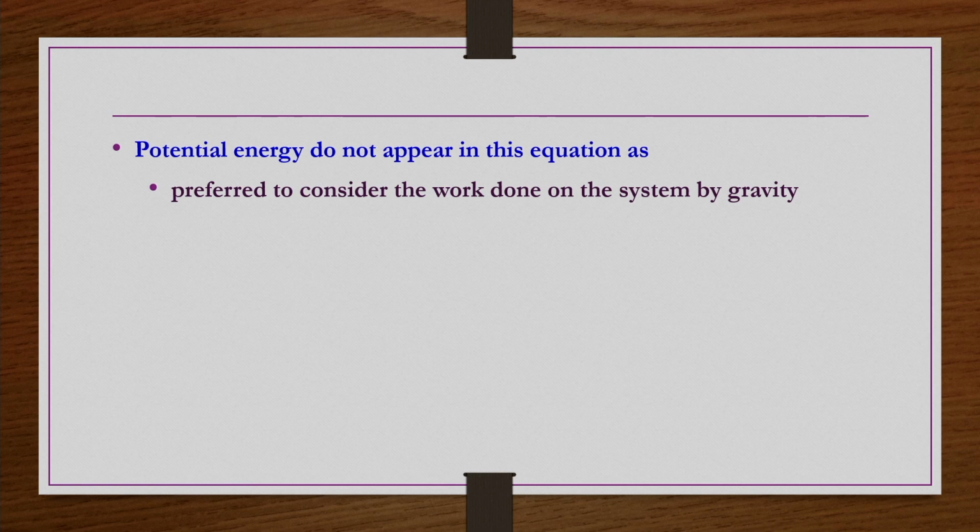In addition, in most of the chemical engineering problems, viscous dissipation or viscous heating is a kind of important physical process, right. So, then that should also be included, but that also we have not written separately in equation number 1. Why? Because the viscous heating part has already been taken care of in the term rate of work done on system by molecular mechanism.